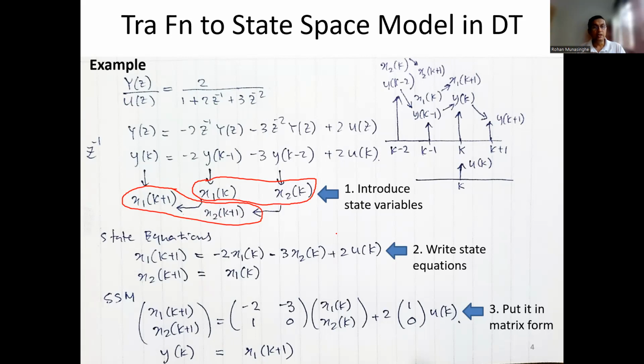So it's very elegant. Remember the format, right? So you convert the difference equation to this format. Forget about the control signal, right? Look at the response, right? Present time, one step ago, 2 steps ago, 3 steps ago, like that. You write it like that and keep assigning state variables starting from the oldest one.